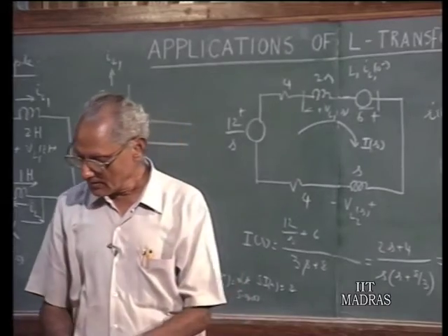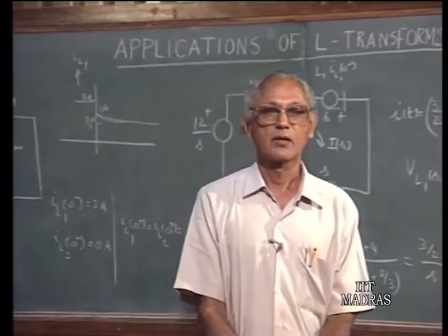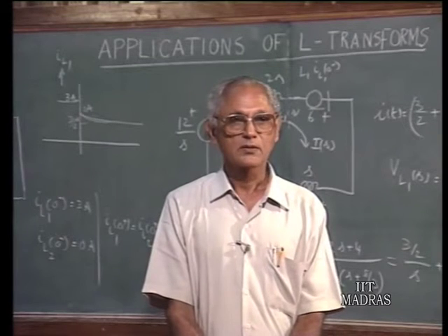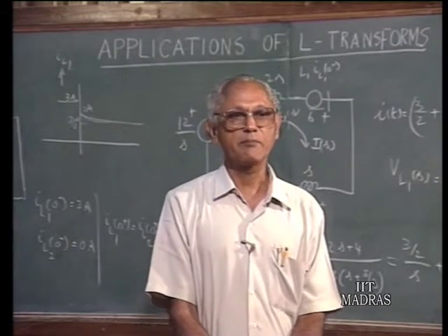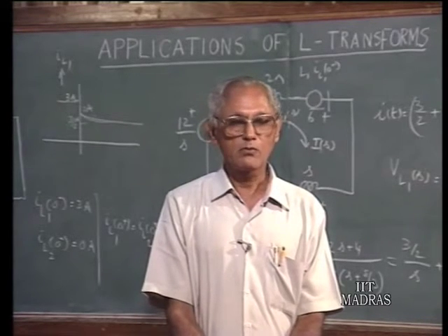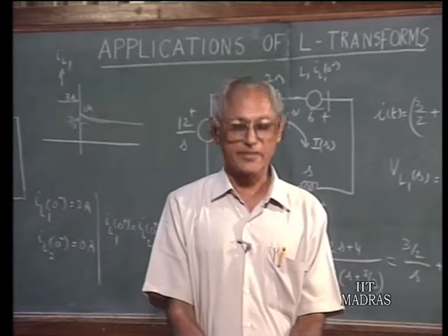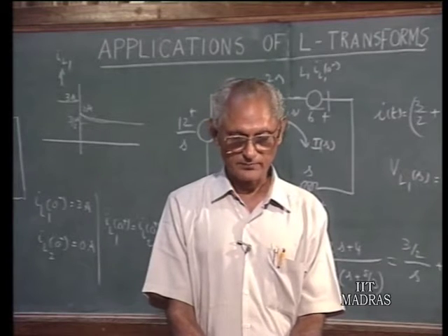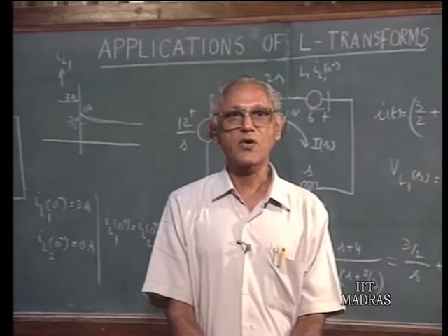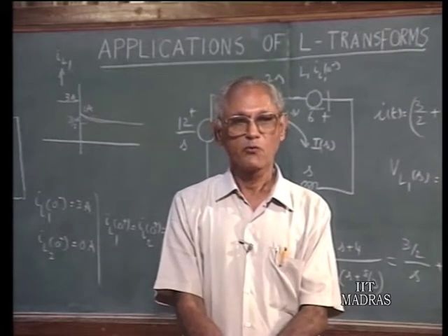But at this time, from what we have seen, let us now see what are the advantages of the Laplace transform domain in the transient analysis of electrical networks. We find there are a number of advantages compared with the classical differential equation approach. First, when you have functions of time which are discontinuous or which have discontinuous derivatives, like your step function or ramp function, then the Laplace transforms of these time functions turn out to be simple expressions,